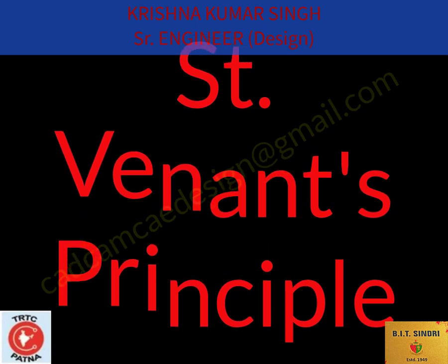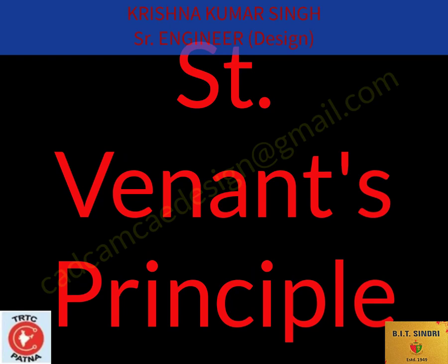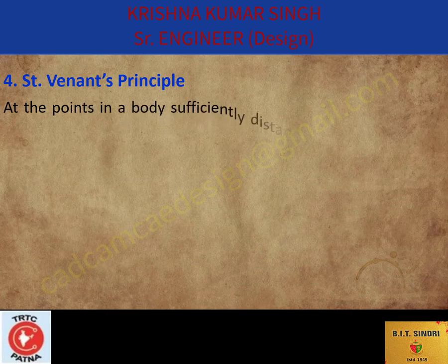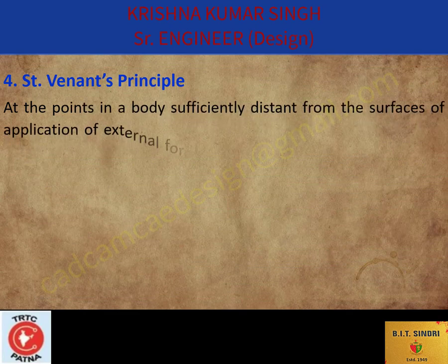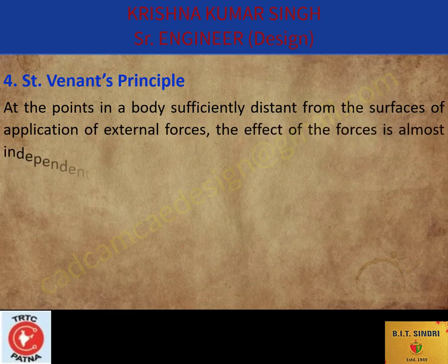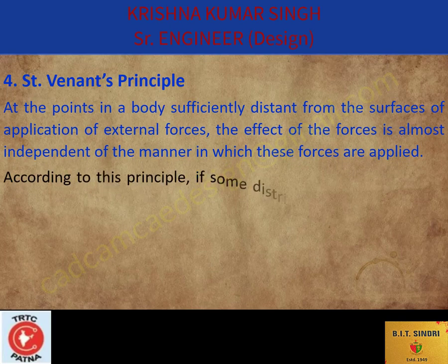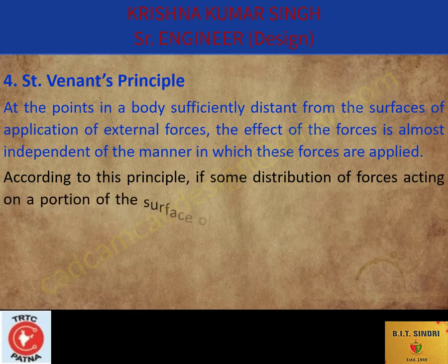Another important principle that will be used widely in our study is due to Saint-Venant. This principle in its general form may be stated as follows. At the points in a body sufficiently distant from the surfaces of application of external forces, the effect of the forces is almost independent of the manner in which these forces are applied.